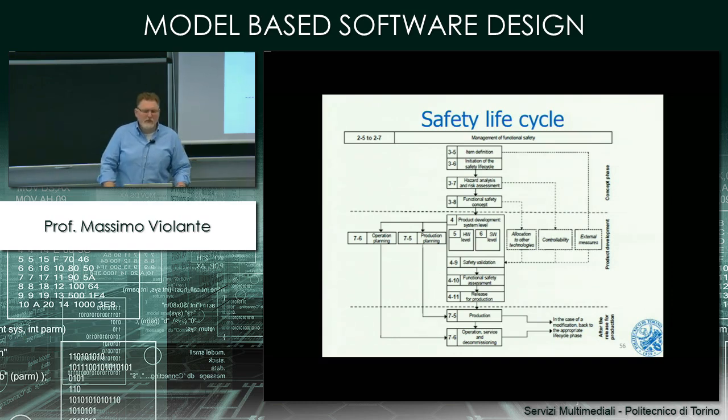If there is a problem with the communication channel that provides the speed of the vehicle, the ABS is not able to operate correctly. But in order to continue to provide service to the driver, the ABS will work in a degraded mode. So somebody recognizes that the fault can happen, and this is the functionality that is activated when we are not able to provide the full functionality.